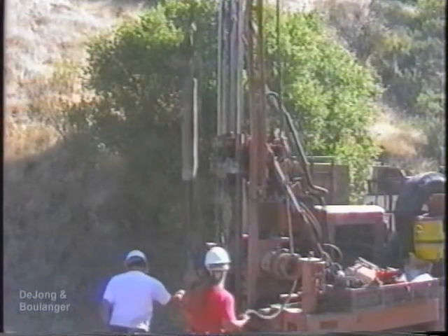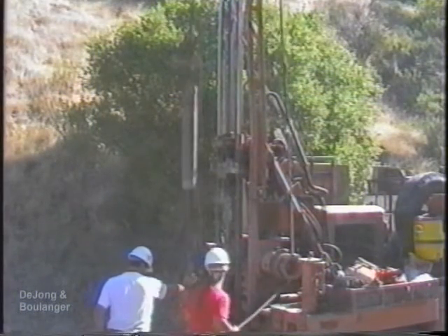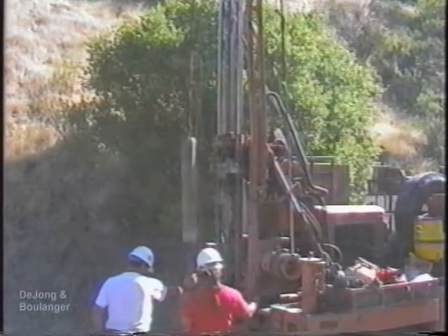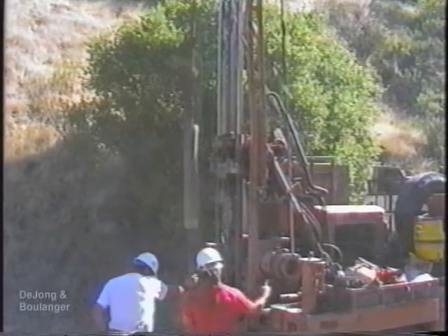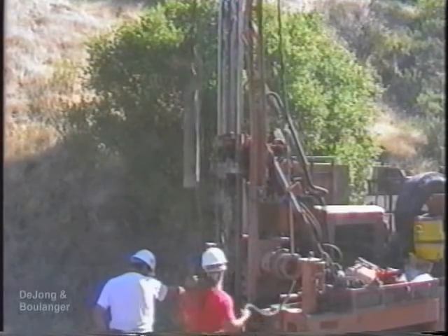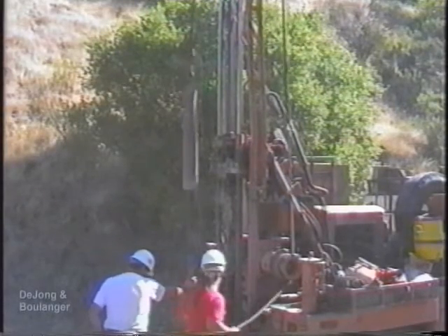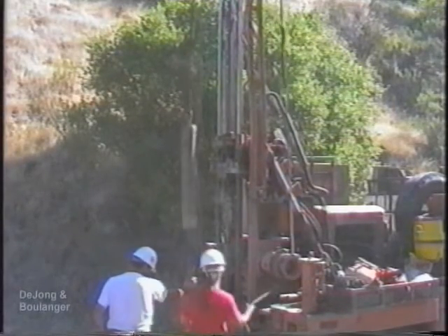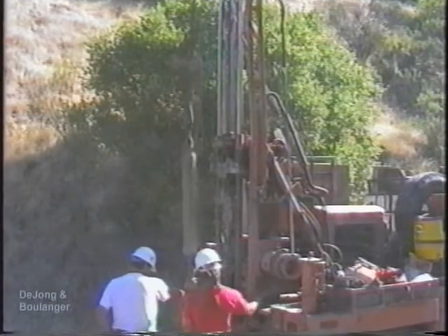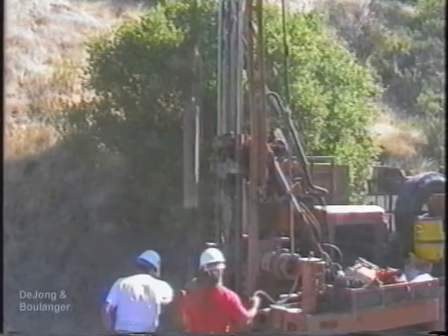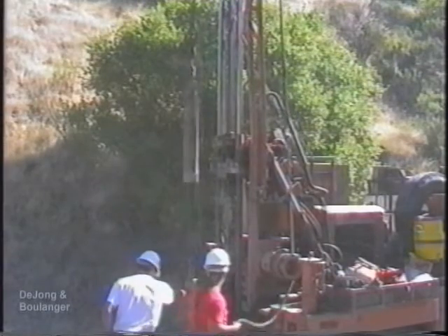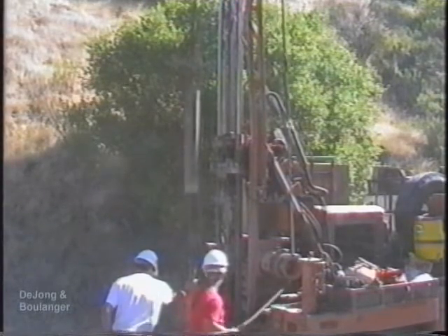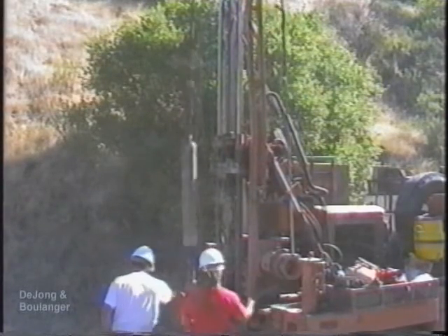Disturbance to soil samples does not just occur during the sampling process. Additional disturbance occurs because of the unavoidable changes in soil confining stress. During transportation of the samples from the field to the lab, or during storage at the lab, especially if significant moisture content changes, temperature changes, or tube corrosion occurs. During extrusion of the samples from the tubes prior to testing, and during handling and mounting for testing.